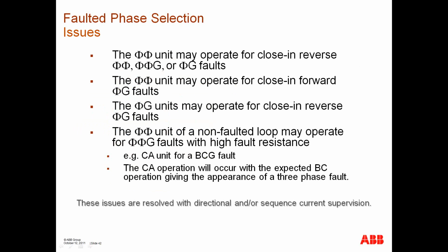And on this page, there is a list of several factors. I will let you read them. But basically, these are issues that are resolved with directional supervision and/or some type of sequence current or voltage supervision, so that you can easily manage these conditions.